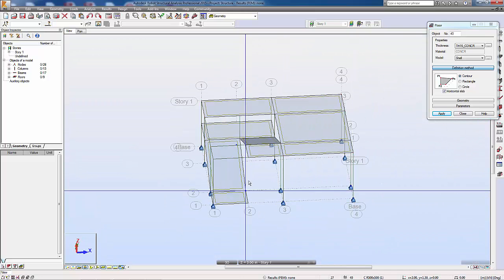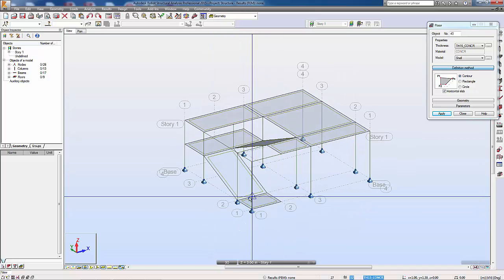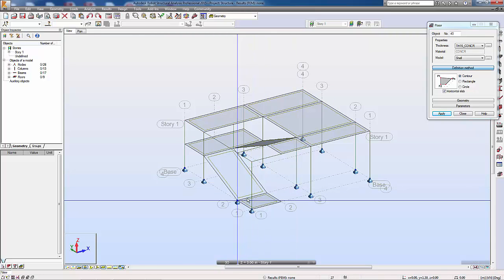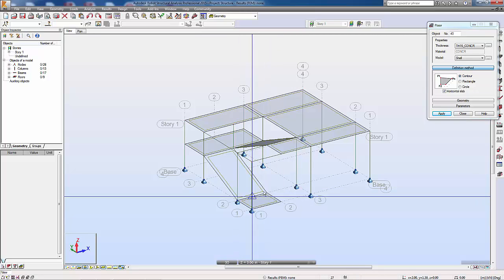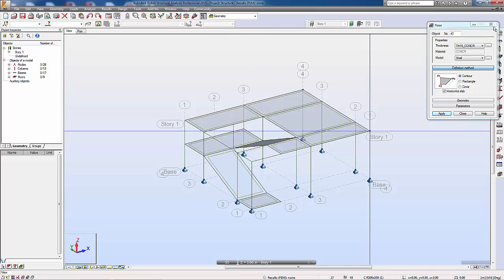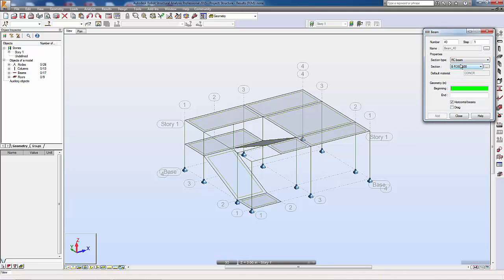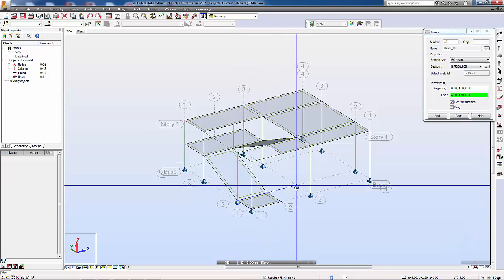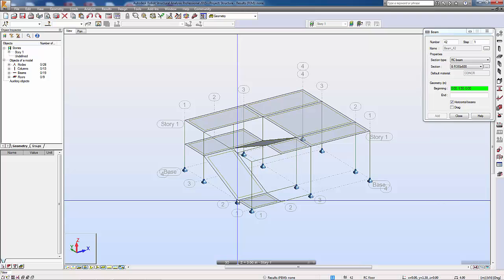Okay, so normally along this line, one single slab to support this one, normally we consider is not strong enough. So in general, we should put in some column support in here, and then beam connecting here. So what we're going to do is create some beam to support this one from this point to this point. Okay, and from this point to this point. Okay, and then also it's better to put in